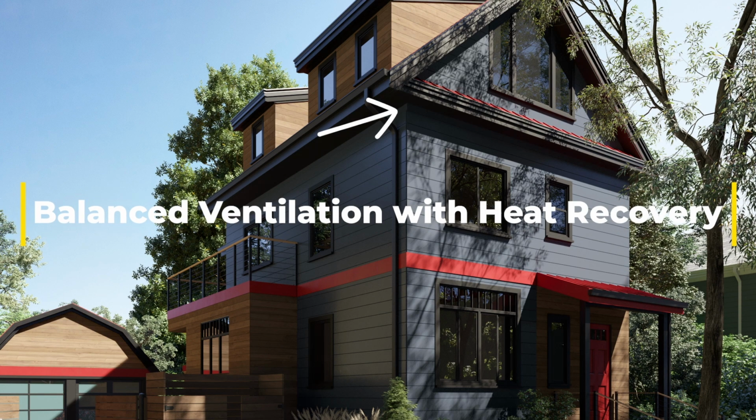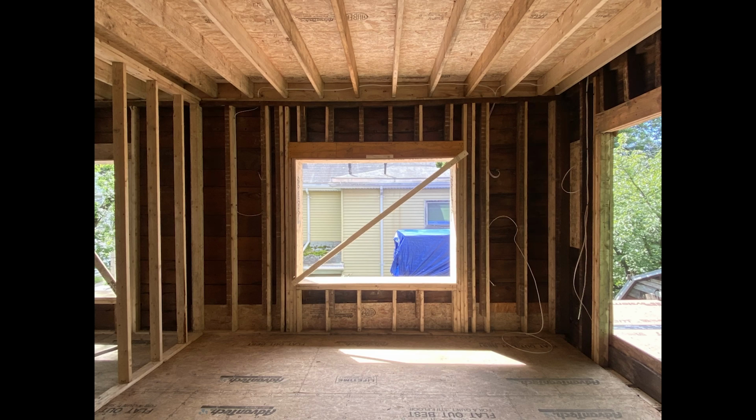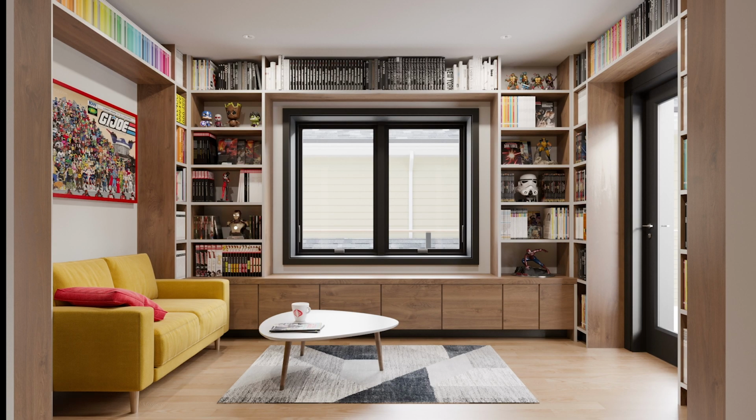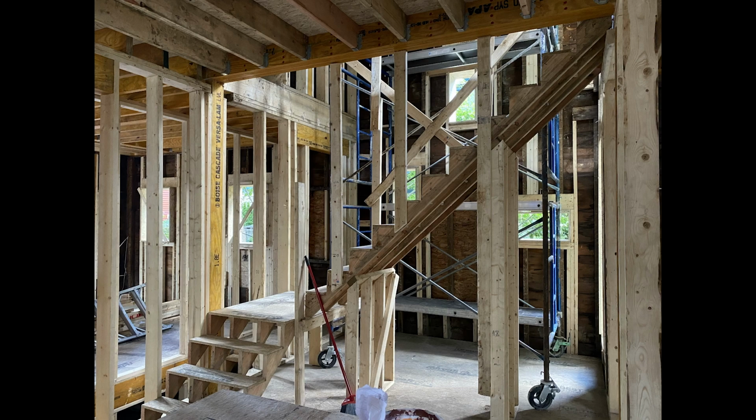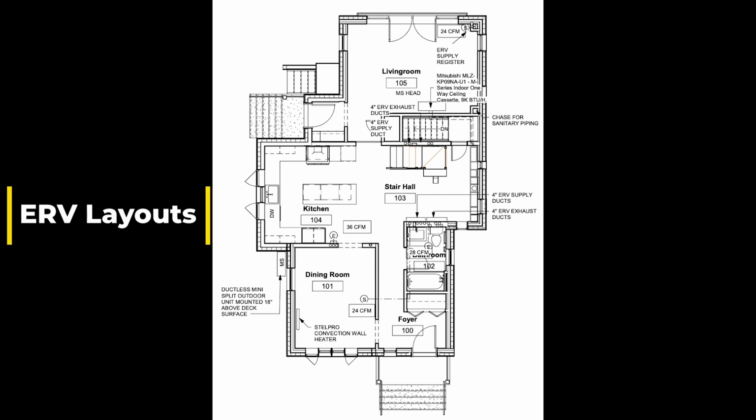And so here's a really important factor: in passive homes, the air is brought in and out. These are some renderings of what the home will be. It's a Tetris wall. And instead of air just blowing around the home, we use an ERV system, which stands for Energy Recovery Ventilator. What that does is it brings air in and replaces the stale air with fresh air. And while it brings it in, it is conditioning it.